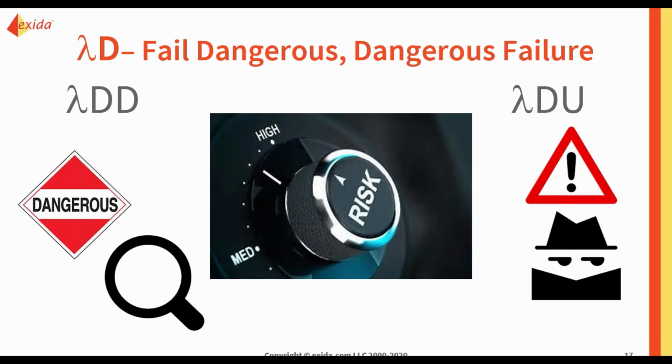And as I said, these failures are the super important ones. These are the ones to keep your eye on. These are the ones to really know about. They're going to be on the back of the certificates, in the FMEDA reports. They are the ones that are going directly into the SIL calculations that end users do. That's why they're so important. So not only knowing this number, but making sure it's credible, justified, traceable, realistic is absolutely key.